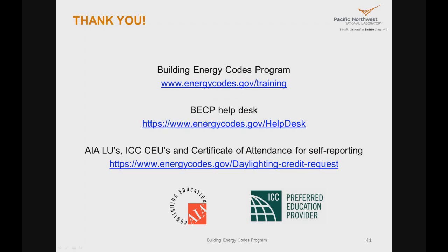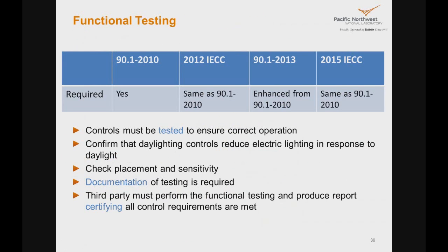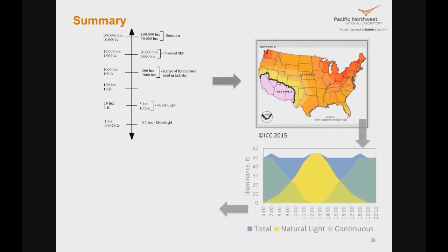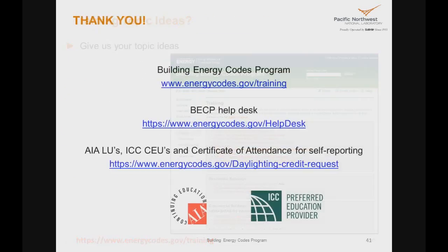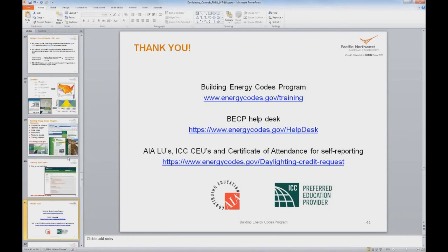Yes, it is. Okay. So this has to do with side lighted zones and the one times the head height and the secondary head height, Rahul. So right. In 90.1 2013, the secondary side lighted zones are only 1 times the head height in depth, but extend that depth beyond the primary side lighted zone. Isn't the 2 times the head height a misnomer to the depth of the space? Right. That's true.